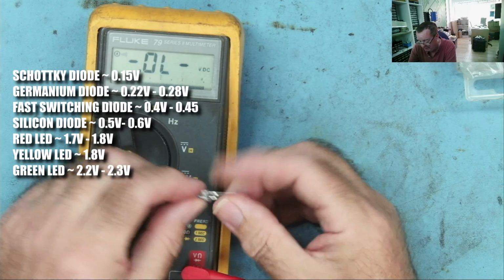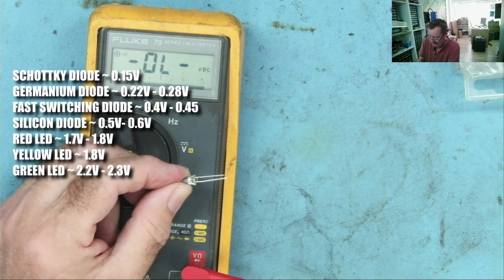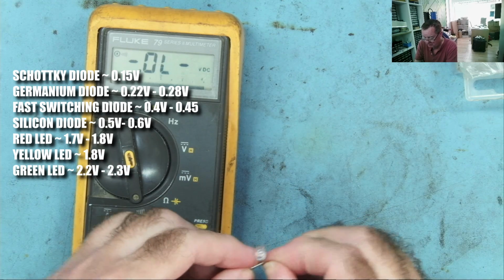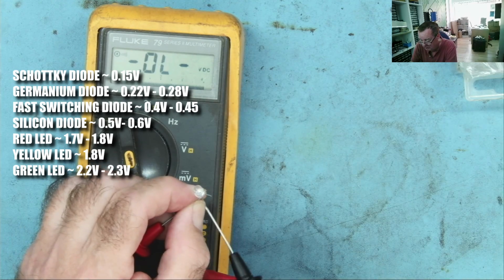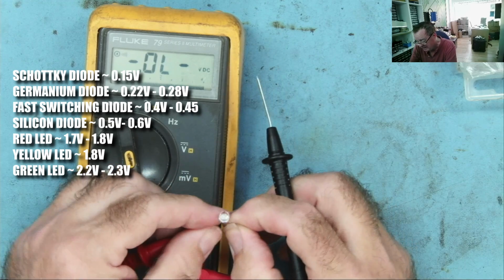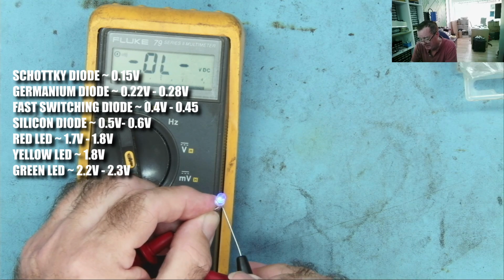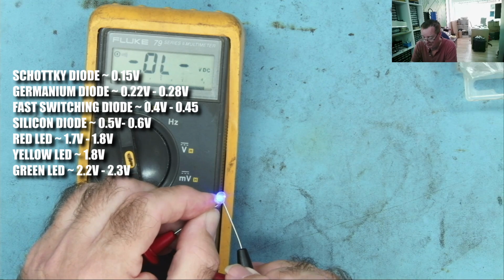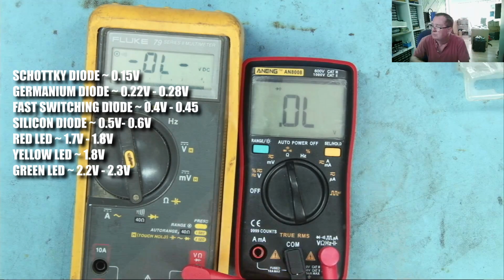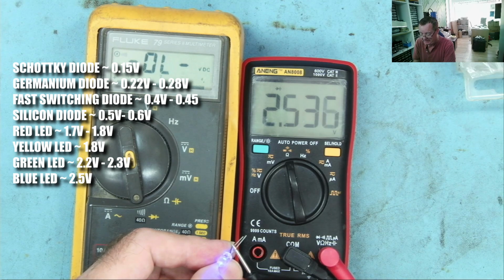Now to a blue LED, again the longer lead here being the positive, and it's like the small terminal inside it. Okay, so we check this one. Lights up blue, you can see, but this one is actually not reading on my meter. The voltage drop is up very close to the maximum reading on diode mode. Okay, on some multimeters it will read. And try this one. Yeah, 2.54, you can see it there on that one.